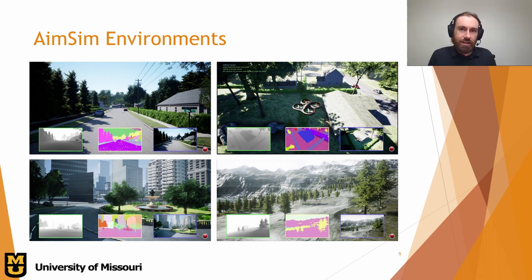In AirSim, we've got access to a camera that gives a color image, a depth image, and a segmentation image using the exact known distances and object labels. And we can control the drone with either simulated physics using the flight controller or use a special computer vision mode to position the camera directly. And that can be useful for some applications where we really just care more about the simulated imagery rather than the actual flight physics.